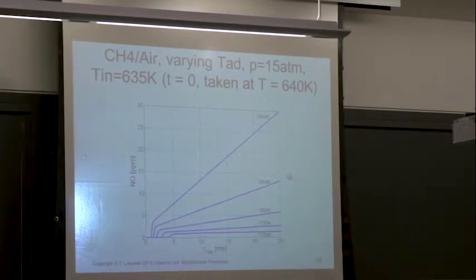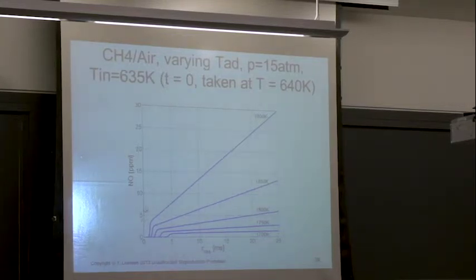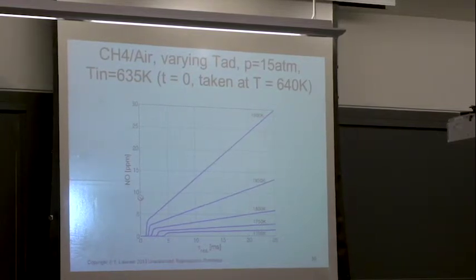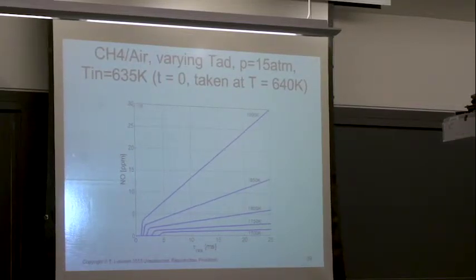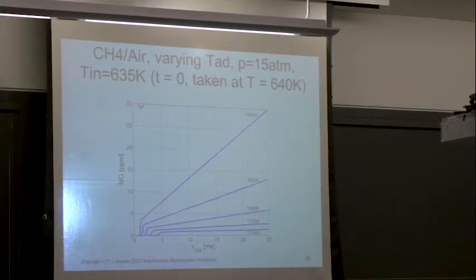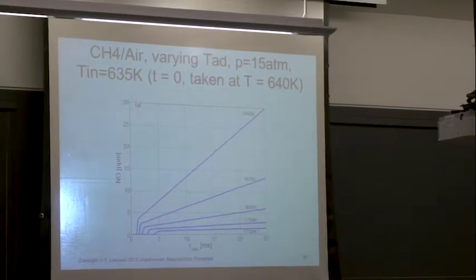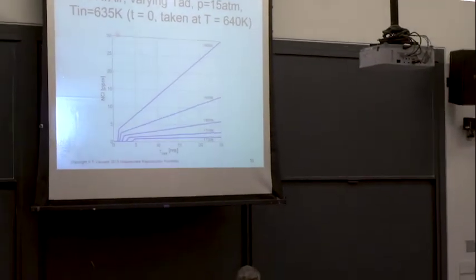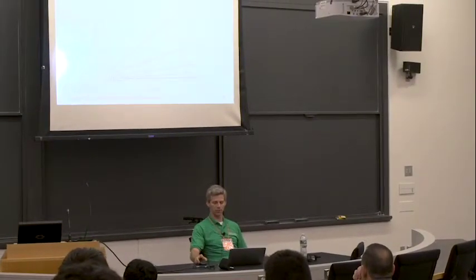And like I said, in many regions in California, NOx regulations are as low as 3 ppm. Many regions in the US are 9 ppm. These are state regulations. And then the US Environmental Protection Agency sets a regulation of 30 ppm. That's the national standard, but then there are lower level local standards. The World Bank, in order to loan money to a developing country to build a power plant, their number is 30 ppm. So that gives you some context for, well, if you want to do 30 ppm at 1850 K, you're going to have to keep your residence time below, I don't know, 75 milliseconds or something like that.